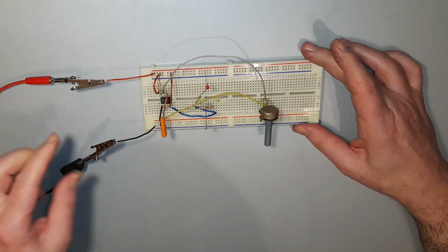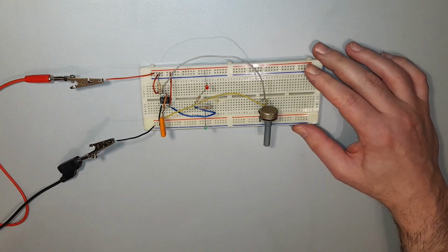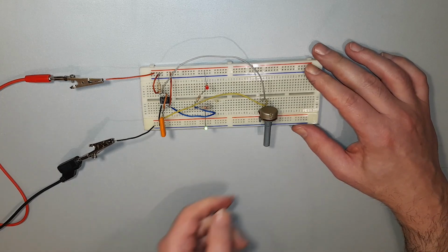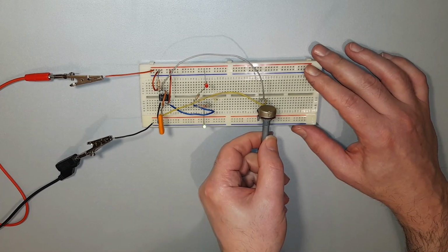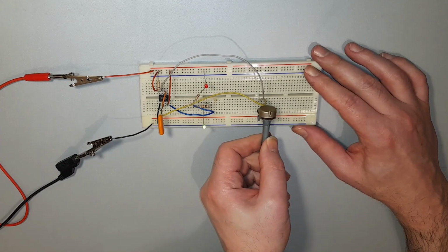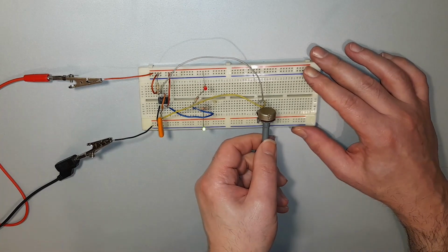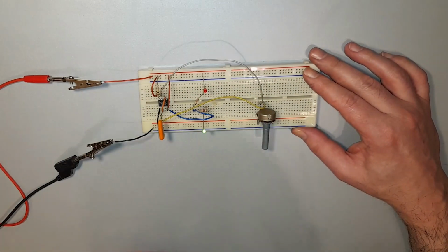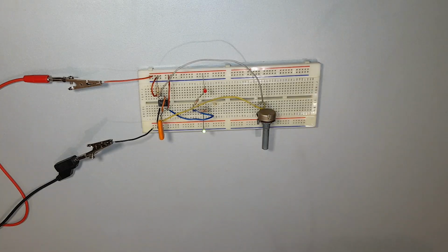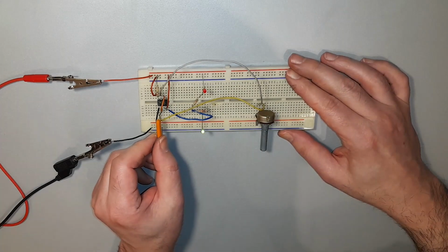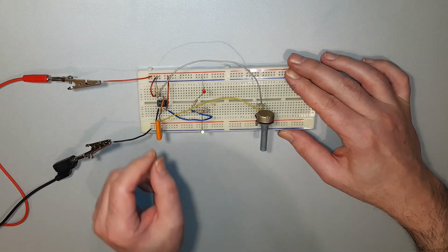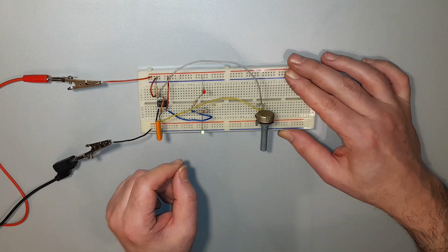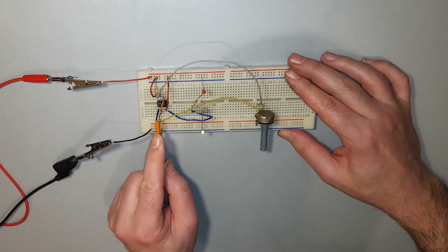Now we can slow down to normal speed, turn on the power and see if the circuit works. As we power up the circuit, we can see the green LED appears to be continuously on, and the red LED is very dim. Adjusting the potentiometer appears to have little impact on the circuit's function. I had these kinds of teething troubles in my last video too. But this is no accident. The capacitor is small in value. It is a 330 nanofarad capacitor.